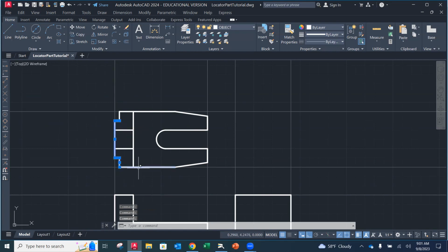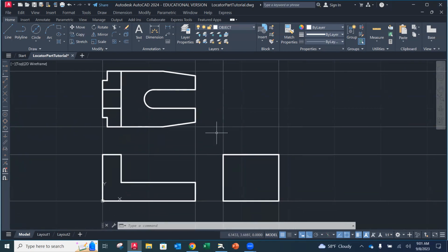Okay, you can kind of go around here. If you start selecting and you have add-on lines or extra lines where it didn't go all the way to the edge, but then you added on a line, you don't want to do that. You want to extend those lines, and you want to make sure that you're making it all the way to your intersections. Okay. Has anybody had any of that where they've been like, oh, I'm just going to kind of clean it up? Don't do that. Make sure that you start over and you have continuous lines that aren't on top of each other and are to their endpoints and trimmed nicely.